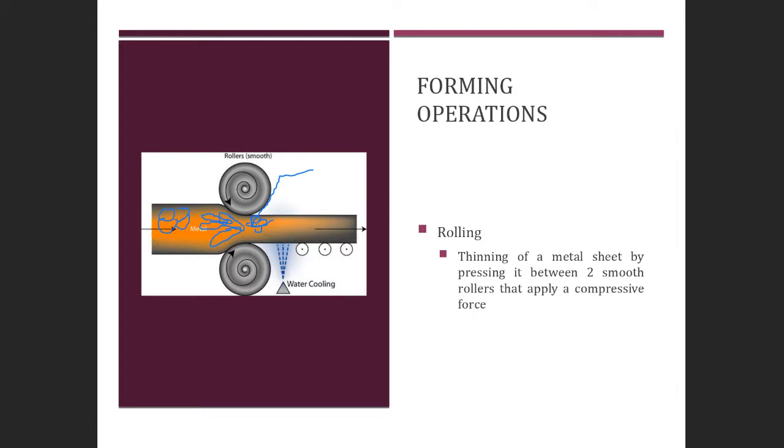And so you end up with a finer grained structure. So your mechanical properties will then be higher for strength, hardness, and things of that nature. If this was a cold forming process, then you're going to end up looking at elongated grains from this moment on this way. They're just going to be pancaked, elongated grains, and that would be your cold form process.